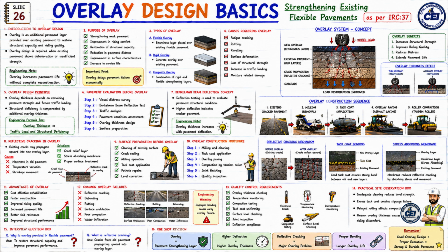Now let us look at the 10th topic. Overlay construction procedure. Step 1. Milling and cleaning. Step 2. Tack coat application. Step 3. Overlay paving. Step 4. Compaction by tandem roller. Step 5. Joint finishing. Step 6. Quality inspection. And overlay durability directly depends on the construction quality.